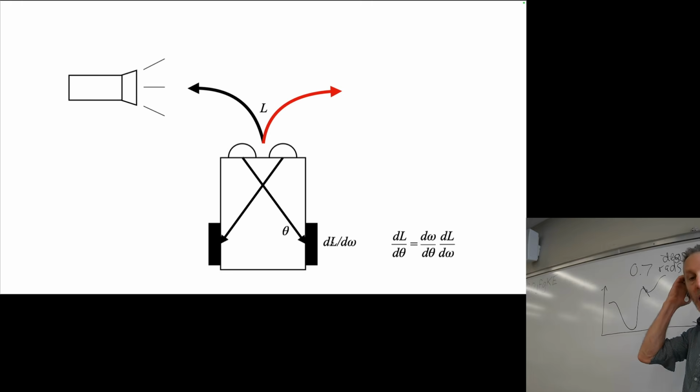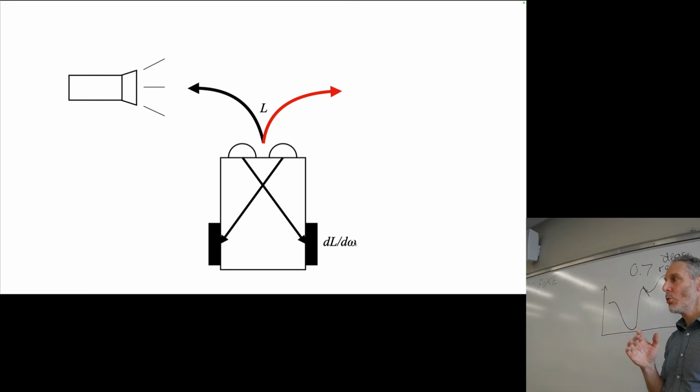Let's assume, remember that omega is being set by the physics engine. So we're not going to take this gradient information and change omega because we, the human, or we, gradient descent, we're not responsible for this variable. The value of this variable is being set by the physics engine. So we know how omega should change to make this robot do more of what we want it to do, but we don't have ownership over this variable. So we skip over it. We've computed the gradient, but we haven't applied the gradient.